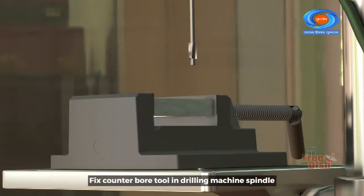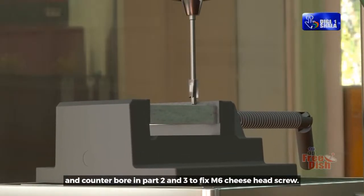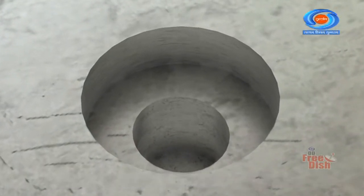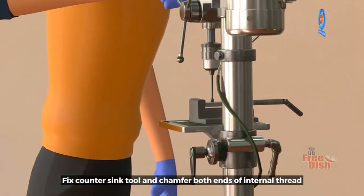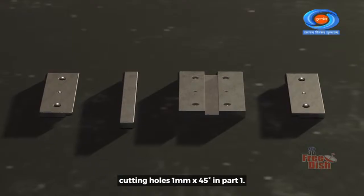Fix counterbore tool in drilling machine spindle and counterbore in part 2 and 3 to fix M6 cheesehead screw. Fix countersink tool and chamfer both ends of internal thread, cutting holes 1 mm into 45 degree in part 1.